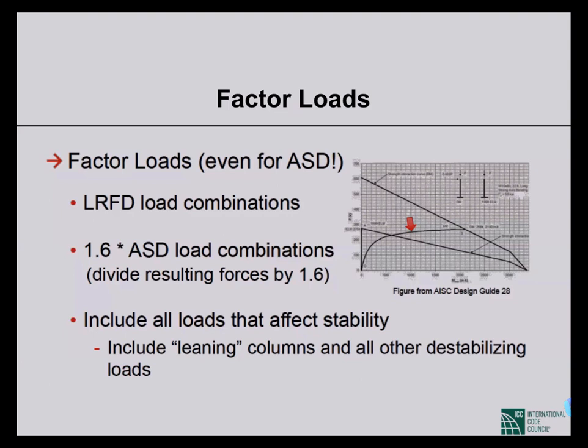But a very important thing is that in elastic analysis, the software analyzes the structure for dead load, for live load, for wind load, earthquake load, and then after all these analyses, the results are superposed.